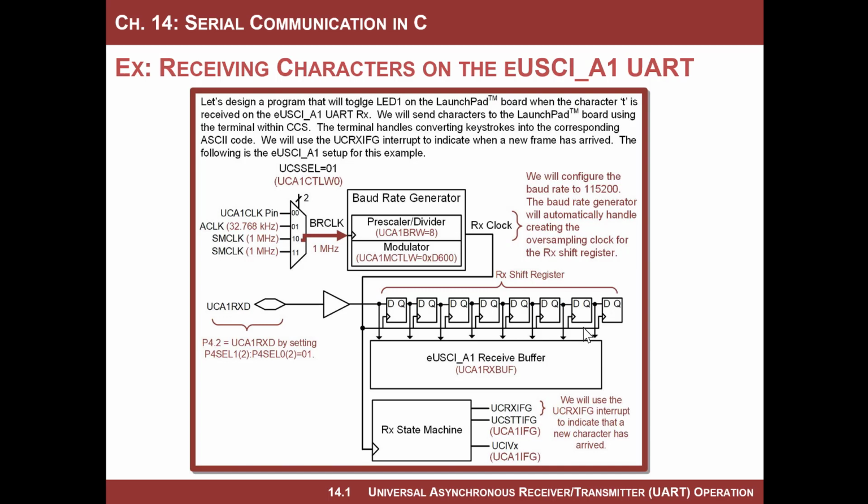So what we'll need to do is set up the receive interrupt, and every time there's a new character ready to be read from the receive buffer, we'll execute an interrupt service routine. That interrupt service routine will go in and say, hey, are you lowercase t? If you are, I will toggle the LED. If you're not, don't do anything. All right, so that's kind of our marching orders.